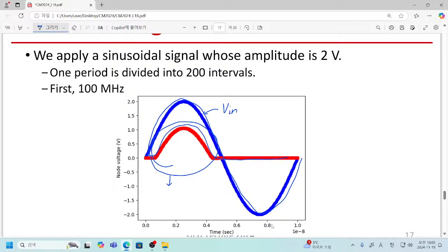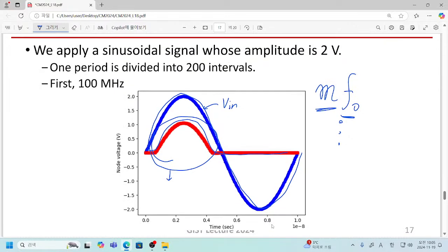So it can contribute multiple frequency components, not only this fundamental frequency, but generally its integer multiples. Fundamental, 2 times fundamental, 3 times fundamental, many kinds of harmonics of this fundamental frequency can be generated by this rectifier. This is what we have expected in our example.